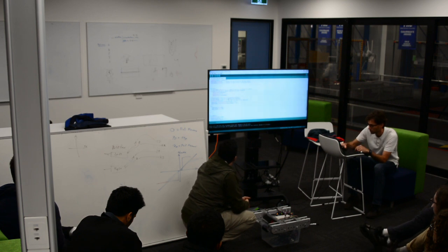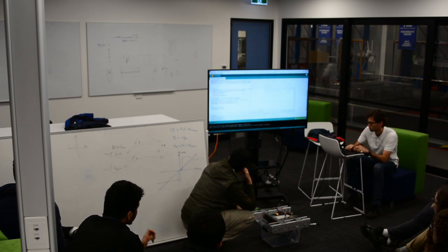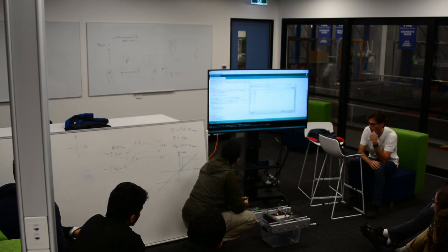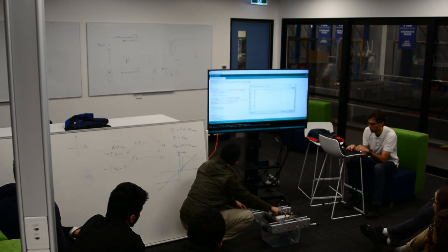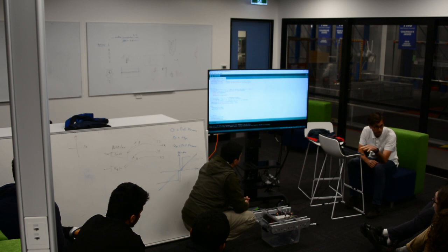Not bad, okay. Let's go even more here. 998 and 990, still pretty good. So no overshoot yet. And I would say you would normally increase them both until you get just a little bit of overshoot. But once you put this on the ground though, the whole amount of inertia changes, right? So right now it has very little inertia because it's just the wheels spinning. Once it's on the ground, the whole robot inertia will start to push it. So overshoot in this case might be, we might overtune it, right? Tuning it off the ground is different than tuning it on the ground.